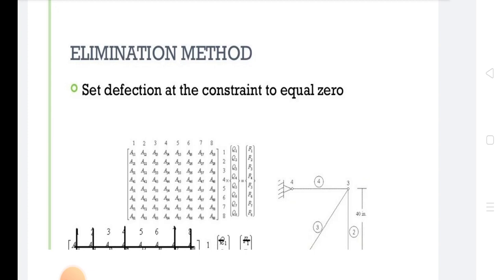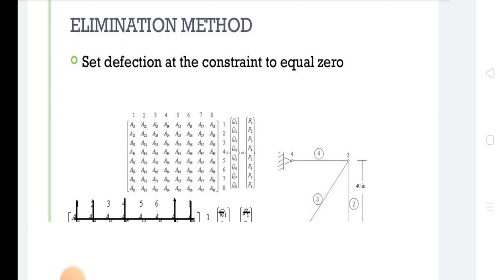In this elimination method, the type of element used in finite element analysis depends upon the type of problem to be solved. The problems may be structural, thermal, fluid and electromagnetic. Selecting a suitable element for a particular problem plays an important role in finite element analysis. Elements can be of different types depending on the discretization process. In general, the different types of elements are one-dimensional elements, two-dimensional elements, three-dimensional elements, and axisymmetric or rotary elements.